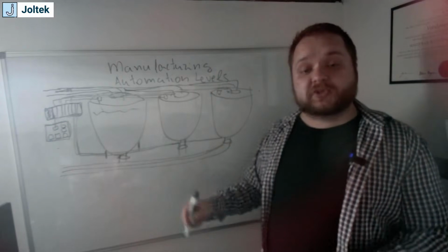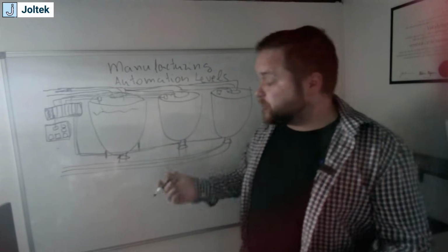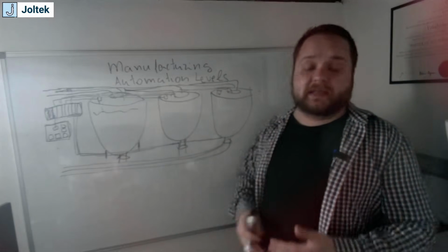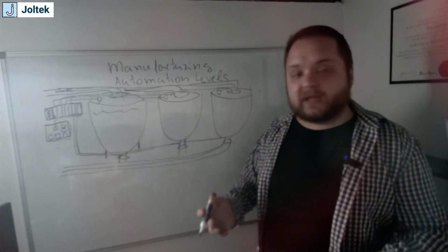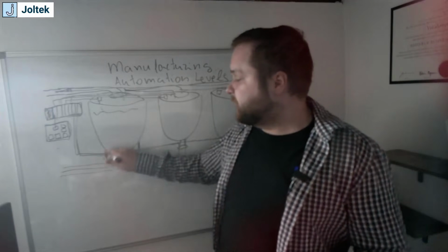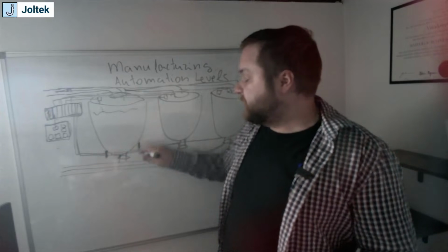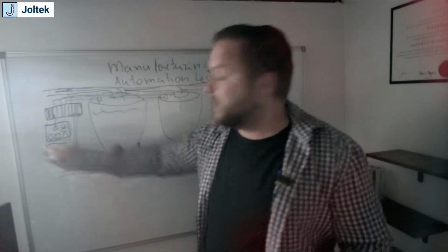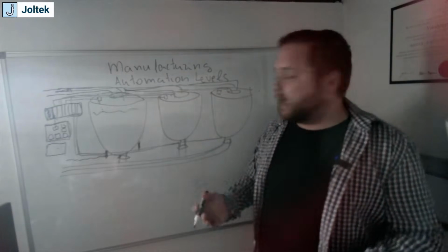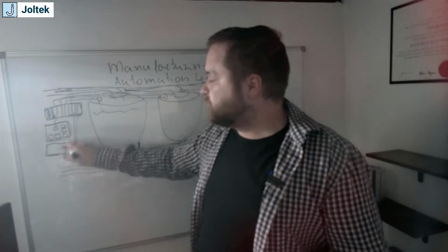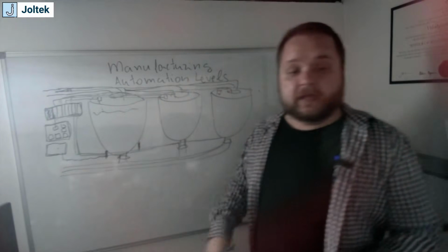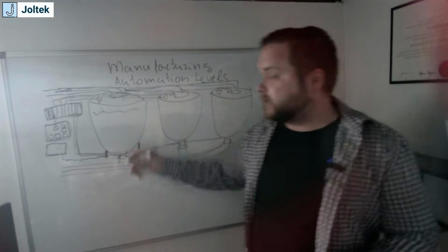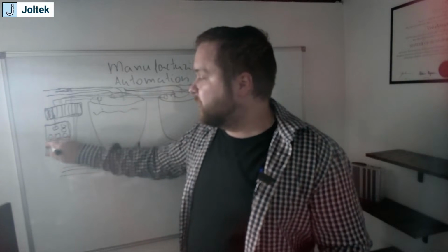So I've already mentioned that some of the load cells, actually a lot of the load cells that I've worked with, are going to be on a network, right? Again, depending on which flavor you buy, depending on the platform, of course it could be different, but ultimately imagine that a load cell is going to be something that holds the tank here. You're going to have a wire, and then you're going to have a card inside of your PLC or electrical panel cabinet, which is going to receive these cables and basically convert the signal based on the weight of your tank into a signal that can be read by your PLC.